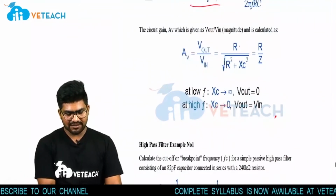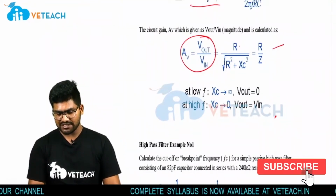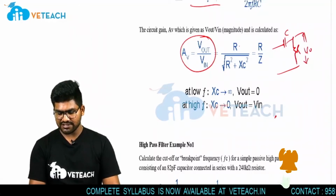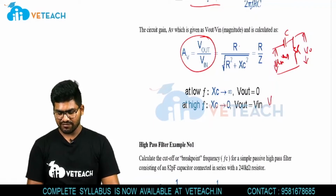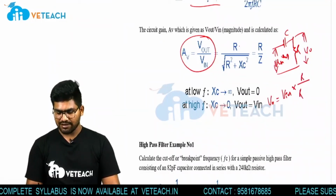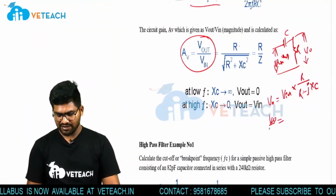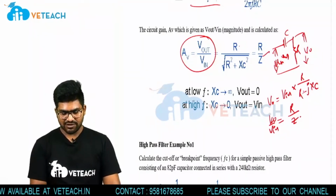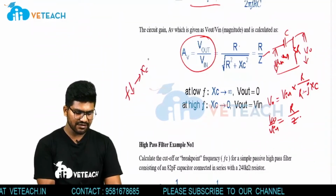Now gain is nothing but output by input. From the RC circuit, this is the V0 output voltage and this is the Vin input voltage. By applying the voltage division rule, V0 is equal to Vin into R divided by the total impedance, which is R minus jXc. So V0 by Vin is nothing but R by Z. Now at low frequency, my Xc will be greater.